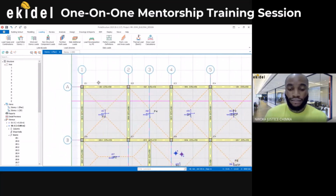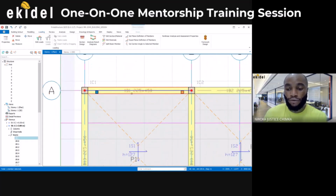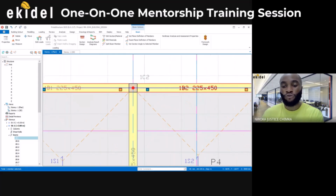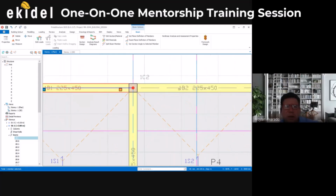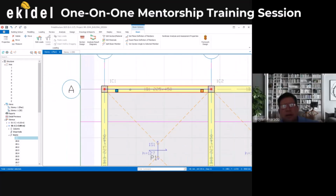And how do I do that? I'll click on the beam now. Let me say I want to hinge this beam. This beam has two ends, I end and J end. Can you see that? I and J. Now it is at the I end that there's an end, because at the J end, there's still a beam going forward, right? Yes, a continuous end. So with that now, I want to hinge the I end.